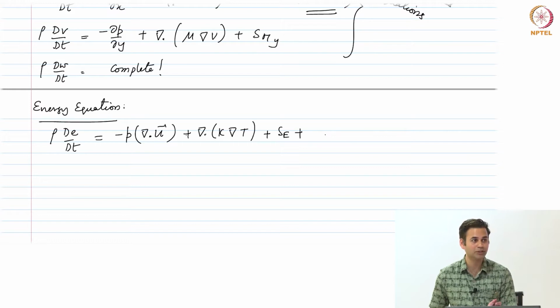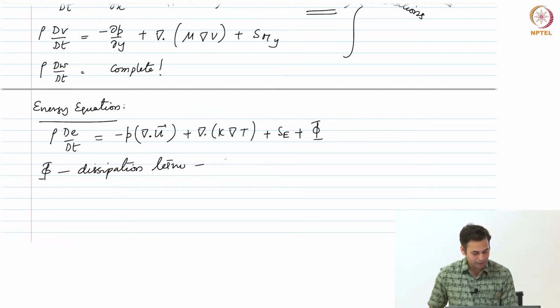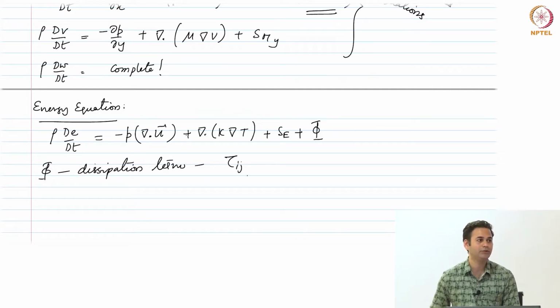We have a lot of terms in terms of shear strains, instead of viscous stresses tau ij. We had about 9 or 10 terms, and I would like to call all these terms phi, okay. So, what I mean by phi is the dissipation term which contains the tau ij terms, right. We had these u times tau xx, u times tau xy and so on.